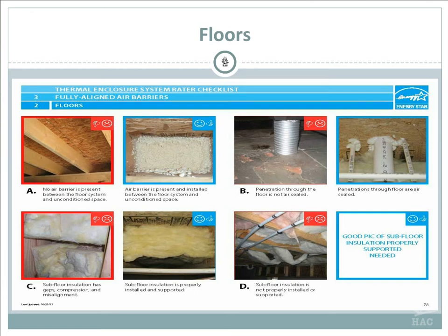The one on the left, I guess that looks like an air conditioner or dryer vent, I'm trying to say. And in there you can see where it hasn't been sealed. Again, on the lower left-hand side, you can see how the insulation hasn't been installed. This is a floor, so you're looking up at this. On the left, you can see where they just cut it, kind of stuffed it. You can tell people that don't like fiberglass falling in their face. But anyway, the one on the right, you can see how that sits in there just right.